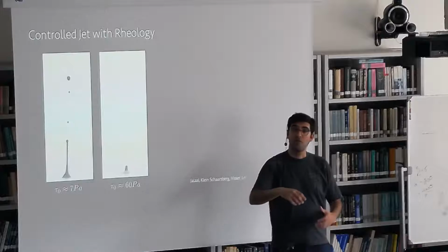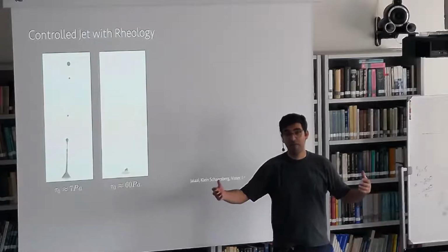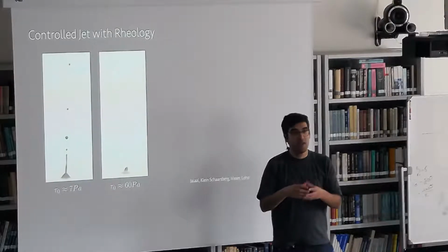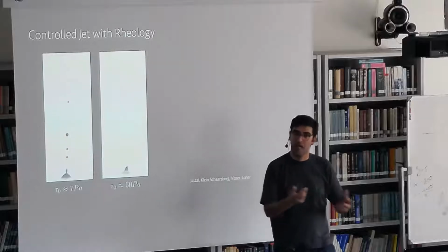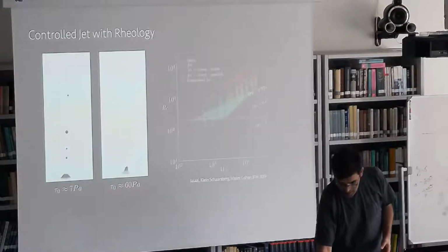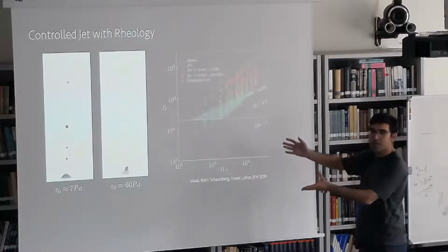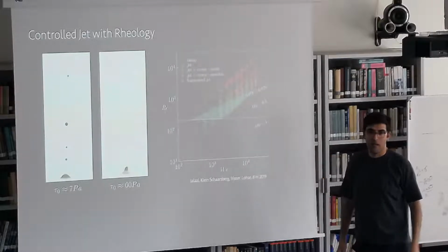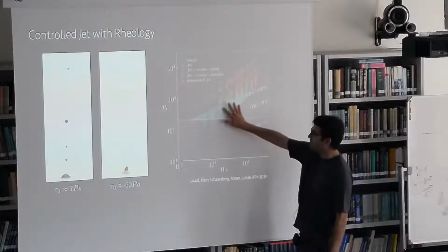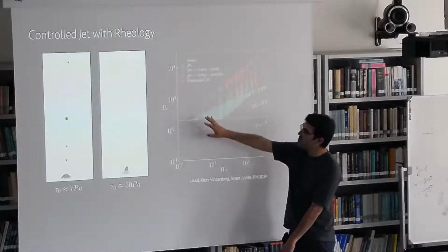We are now able to 3D print circuits at a very, very fast rate with silver paste, which is actually a viscoplastic material, so you can do a rheology. And you can plot it in a phase map, where there is a good regime to do this printing, and that's where this green area is. That's a function of Weber or Reynolds number.